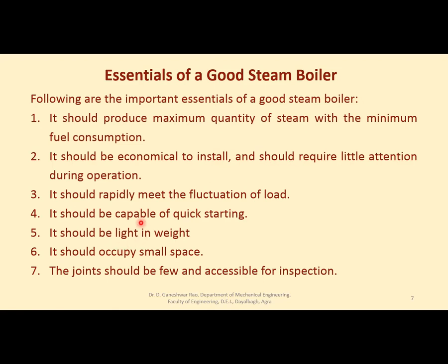Similarly, it should rapidly meet the fluctuation of load. If there are fluctuations of load, that fluctuation has to be met by the boiler so as to ensure proper functioning of the boiler. It should be capable of quick starting. Sometimes boilers take too much time. So if in power plants, etc., a boiler starts in hours, then power production will be affected. Therefore, generally boilers are supposed to start quickly.